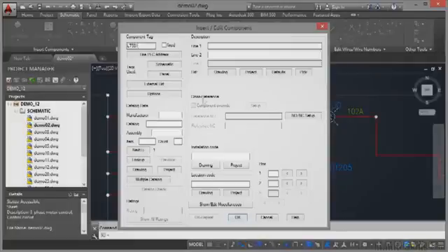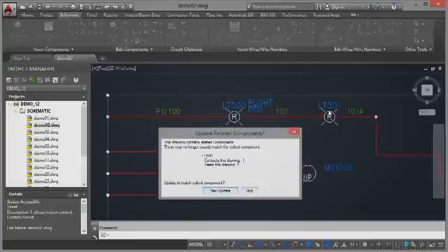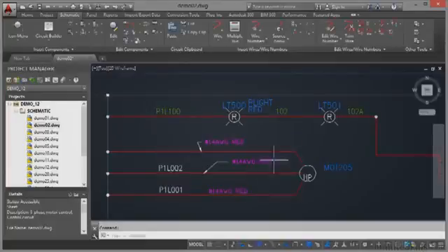So I will do that, change it to 501, click on OK there, that updates, and you'll notice now this drawing contains related components. They may no longer exactly match the edited component. I've got an LT500 just there. Because I've added another LT500, it's telling me, do I need to update the related component here to 501 as well? In this case, I don't want to. I can skip it. But I could update it and they would then both become LT501s. If I skip that though, you'll see I've got a 500 and a 501 on that wire in my AutoCAD electrical drawing.